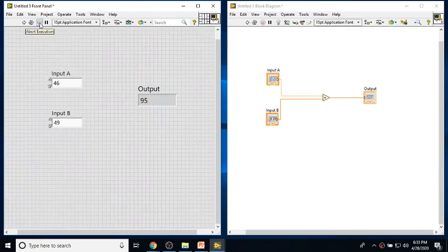The reason why I don't want you to use the abort function is, as I told you, LabVIEW is meant mostly for hardware interface. It's not only for hardware interface, there are many reasons why you use LabVIEW, but more dominantly we use it for hardware interface. Let me say you are controlling a motor, or a boiler or turbine. When you abort an application, the connection between your hardware and your computer, or the LabVIEW where you're executing, will abruptly get broken. So your hardware is left in the very last state that was being executed, which is a very bad habit in industry.